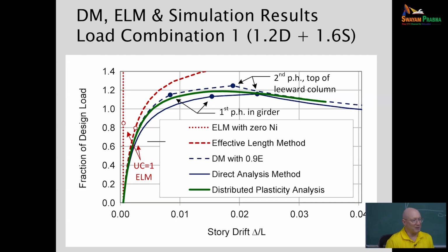Now what's really happening in a structure like this is as we start to fail, we're starting to get a lot of bending of the frame, right? Now with a traditional effective length solution, if you're designing your beams, life is good, I don't see any bending, keep going. We'll do a column design, we've got an effective length factor or our buckling load of the column. The column strength curve is basically tied to the buckling load. So the column design works reasonably well.